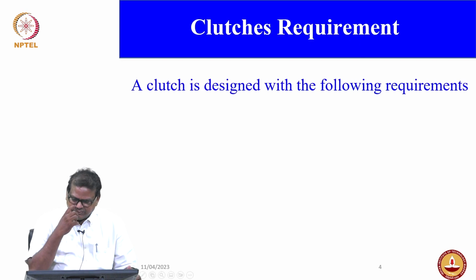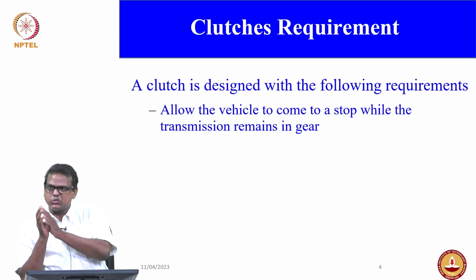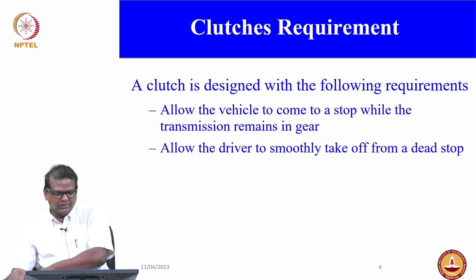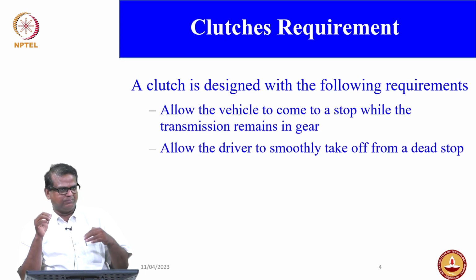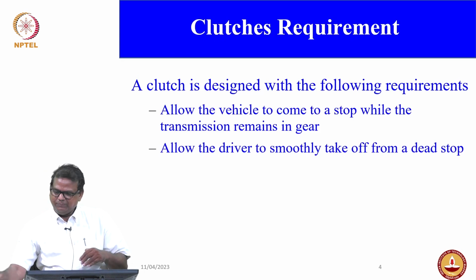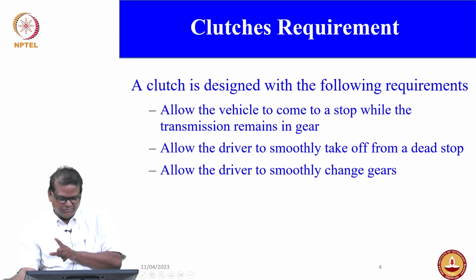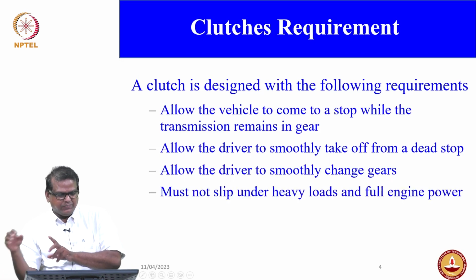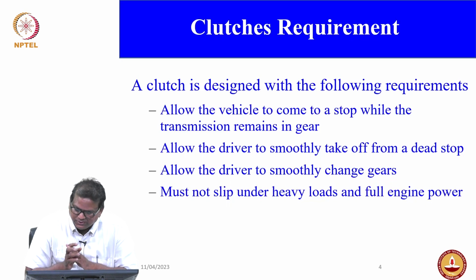The clutch is designed with the following requirements. You can see here: allow the vehicle to come to a stop while the transmission remains in gear. That's one thing. Allow the driver to smoothly take off from a dead stop, and allow the driver to smoothly change the gears. Then, most importantly, it must not slip under heavy loads and full engine power.